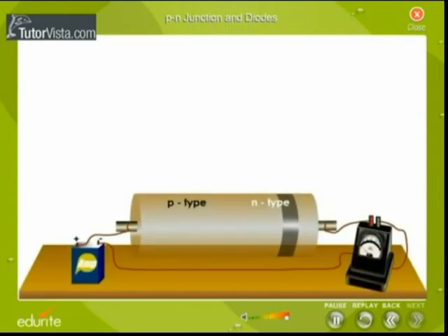Current flows through the junction if the PN junction is connected to the battery as shown here. Holes and free electrons enter the depletion region due to repulsion at the respective terminals. The reduction of the potential difference and the width of this region causes a large number of majority charge carriers to diffuse across the junction. Holes travel to the right and electrons to the left, constituting a current in the same direction.